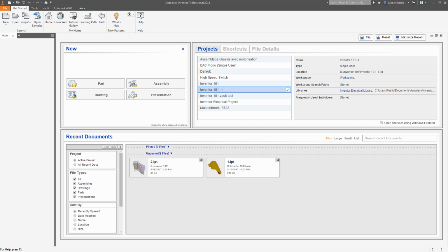So let's jump right in and start talking about what you need to do right after you have Inventor installed and some things you need to think about. The very first thing is the data that you're making. You can store files basically anywhere you want, and a lot of people throw them on their desktop or into My Documents. Well, Inventor has something called projects that helps you handle this all along the way when you're making your parts, assemblies, and drawings, and it makes it super easy.